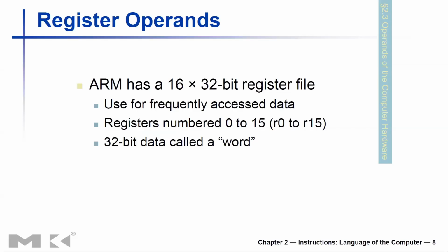Operands, meaning for an addition operation, for an instruction like add A, B, C, you need to store the B and C operands first in registers, and then the result is also going to be stored in another register called A. So for these 3 operands, you need to allocate 3 registers out of the 16 registers available in the ARM processor.